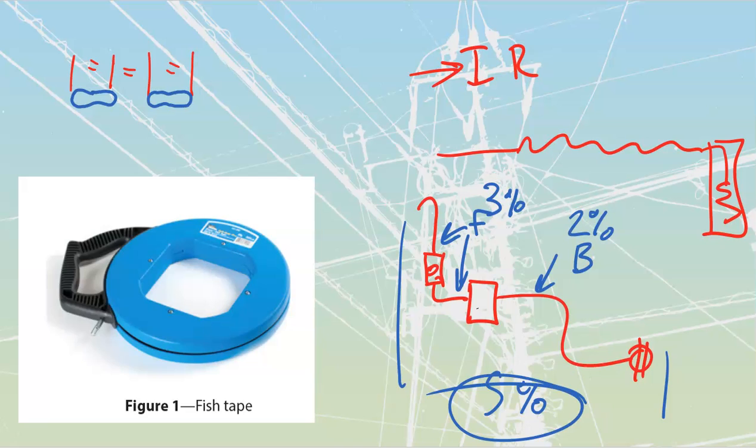All right. Let's talk about components here right now. When we're dealing with installing our conductors, this is where we finally get to take a look at all these pictures that we have over here. They introduce the concept of pulling. When I'm going to insert or withdraw anything into a conduit, we need to have some way to do so. Generally speaking, for short runs, we're going to use a fish tape.